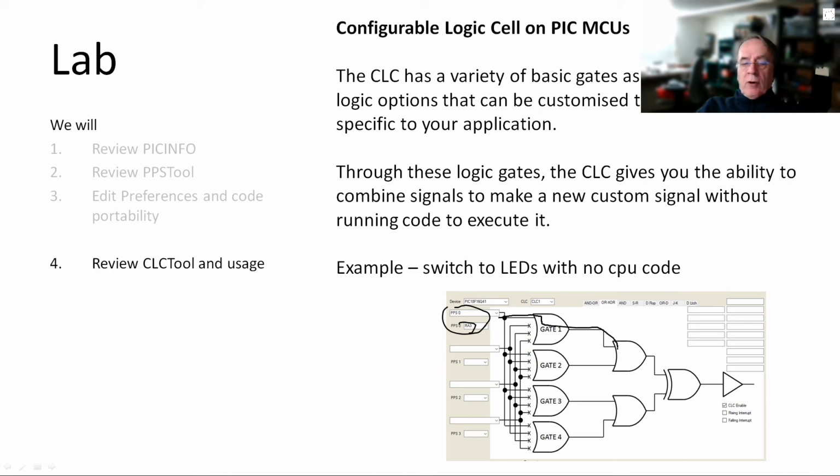It's OR or XOR. It's going to come through, and if I put a high input on RA3, the output will go high as well. You can use this to generate specific outputs. I've used it many times on pulse width modulation that is very specialized, but it does work extremely well, and I'll show you how to do it very simply.